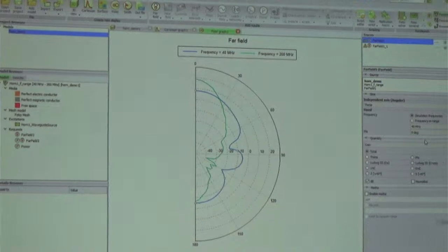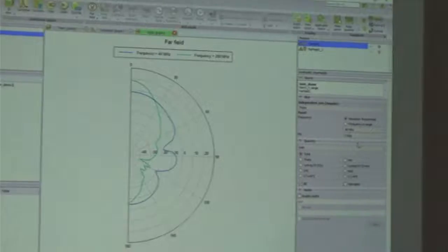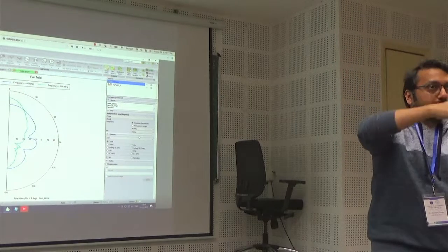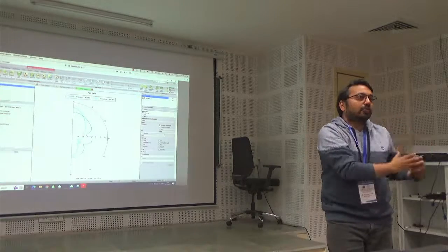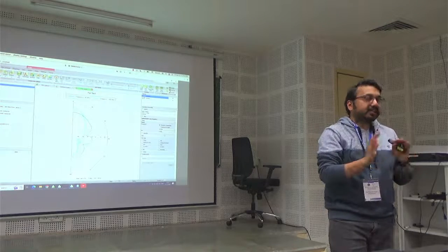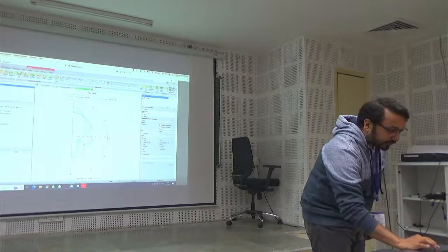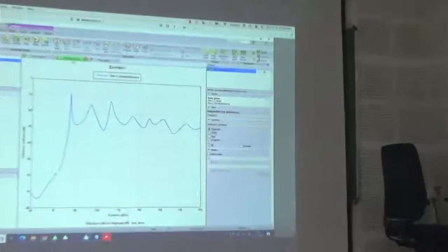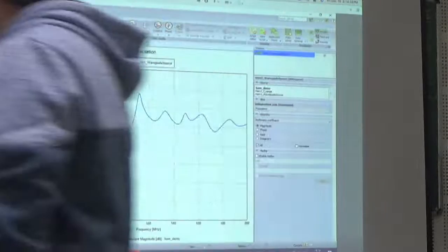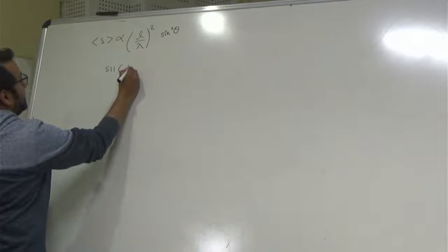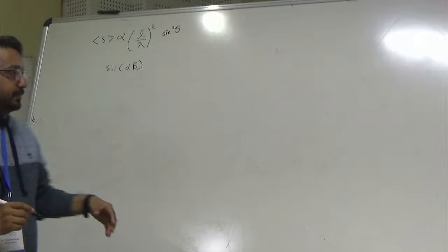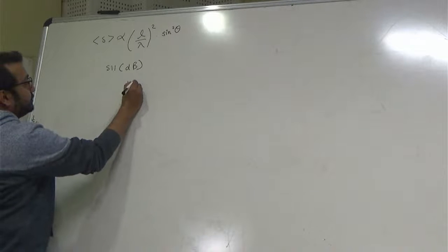So you might want to look at how this transmission coefficient changes with frequency. It's not dependent on your angle, right? It only depends, once you have power at the antenna, on how much of it is transmitted into the system. And that is direction independent. So in antenna engineering terms, we call that return loss. It's a very tricky statement, but I'll just write what is in this plot. What this is showing is what is called S11 in dB units. Not a very helpful unit. You can convert this to linear, that we will call gamma.